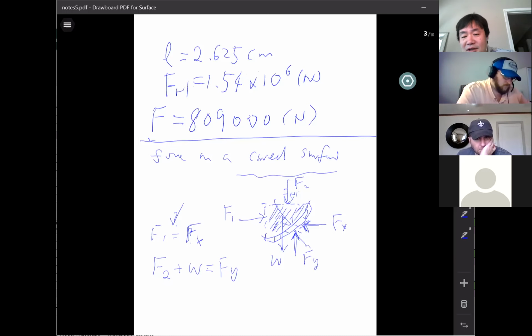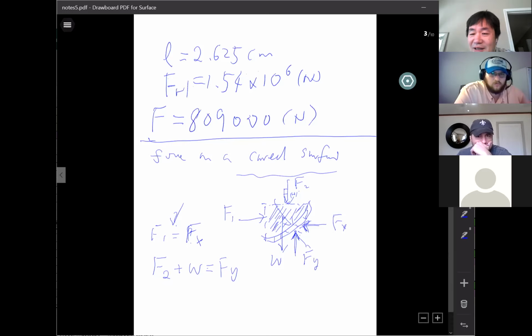Come on, force on a horizontal plane. Before you took this class, you should have known, right? It's just pressure times area. The pressure is the same across the horizontal plane, gamma times h. You don't even need chapter 3 to know how to do it. Just P times A. That's a piece of cake.